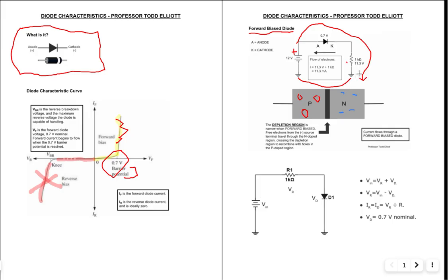Anyway, so using electron flow, because that's the way it really is, and it's easier to explain it this way, the strong negative charge on the negative plate there will, because of opposite charges, drive these free electrons across the barrier, and they will fall into that hole, and then it will recombine and then exit and then go back to the positive plate to complete the current path.